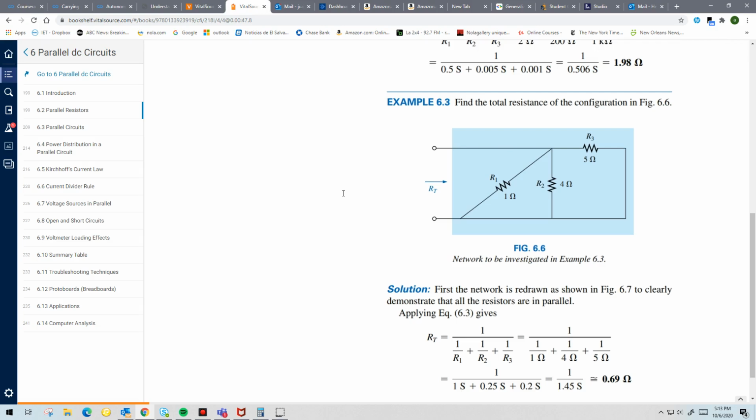The other hint, actually, I'm going to give you 3. That one: you redraw the circuit. The next one is start from the right. See how we really want to know the resistance looking into these terminals? But always start from the right side of the circuit, and then start analyzing what's connected to what and how they're connected.